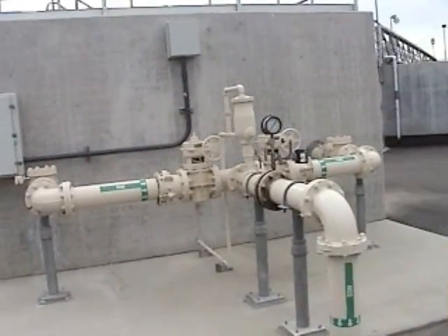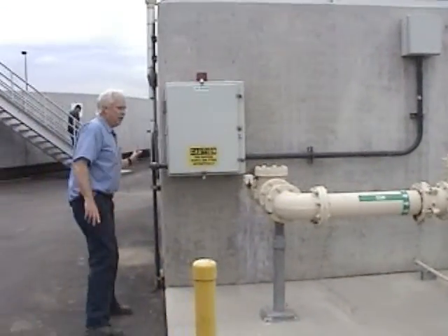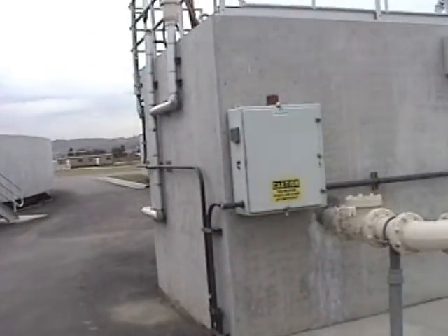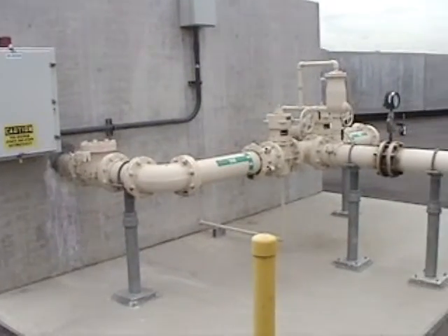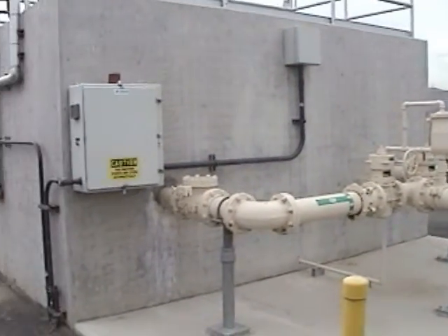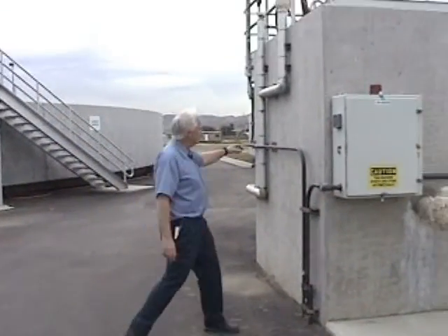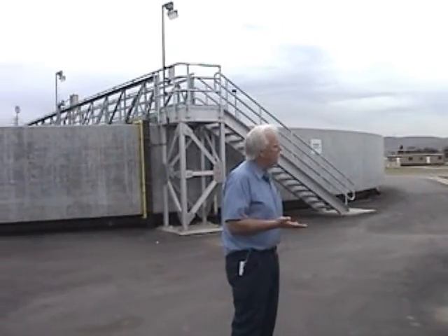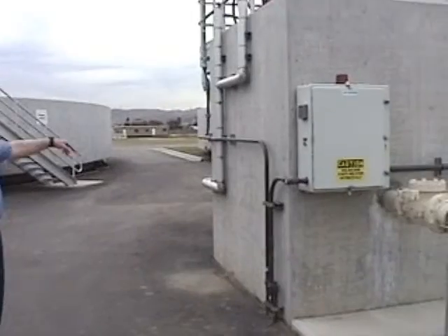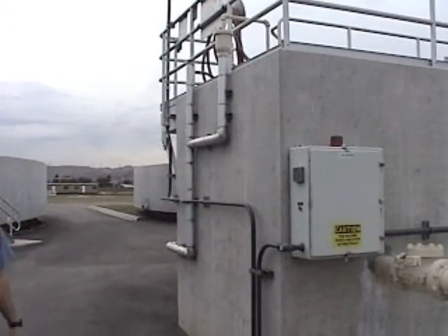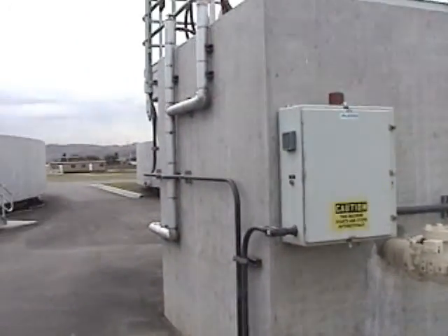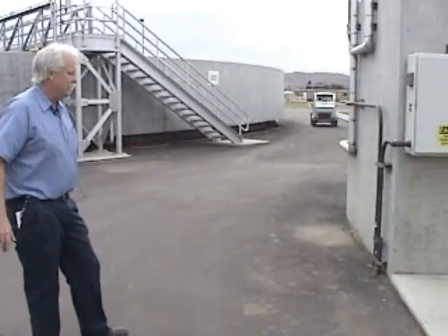This structure right here is the scum removal system. So the secondary clarifiers have what they call ducking skimmers on them, and what they do is they remove any floatables from the surface of the secondary clarifier, and then by gravity they flow into this tank right here. This tank's pumps are controlled by level, and when we hit high level, the pumps will come on and they pump this to RP2. It's really important to periodically check it because the solids will sit in this tank and they can become very thick, and sometimes these pumps will not pump it. So it's important to take a look at that.